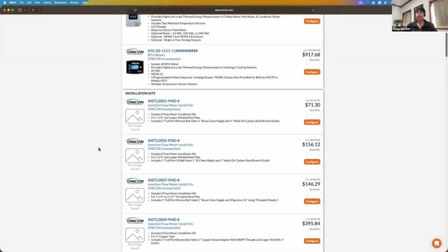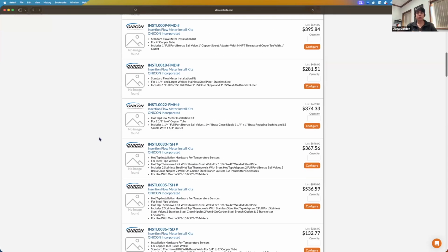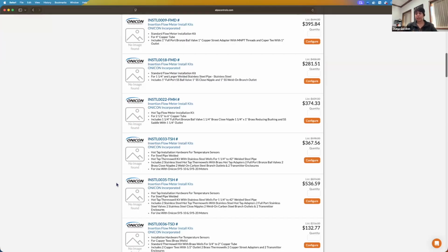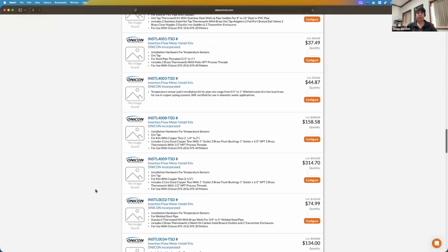But it also gives you the installation kits that you will need that may be applicable for your meter. You have your standard flow meter installation kits, and it all depends on your pipe material and schedule. And if you keep going, it also has your hot tap installation kits. It is all determined by, as I said, your pipe material and your pipe schedule. And as you keep going, you will see that if you did need temperature sensors, if you were getting that FT3500, they do show that as well, installation hardware for temperature sensors.